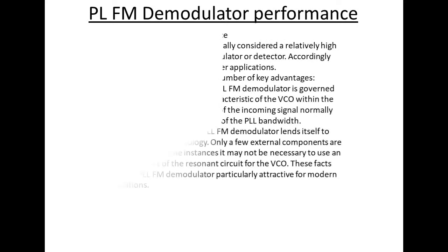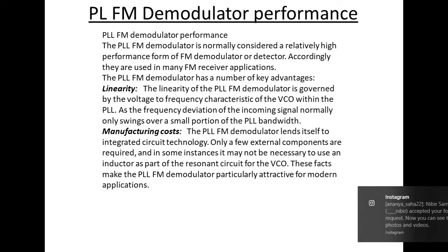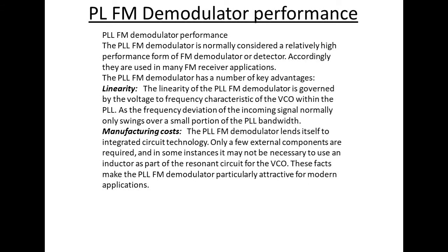Now let us move to the next slide. Let us see the performance of FM demodulator. The PLL FM demodulator is normally considered a relatively high performance form of FM demodulator or detector. Accordingly, they are used in many applications. The PLL FM demodulator has a number of key advantages, like linearity. The linearity of the PLL FM demodulator is governed by the voltage to frequency characteristic of the VCO within the PLL, as the frequency deviation of the incoming signal normally only swings over a small portion of the PLL bandwidth.